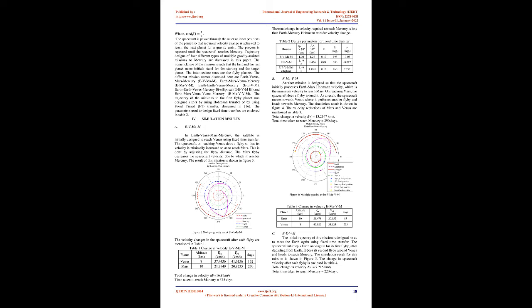3. Multiple gravity-assisted mission. A multiple gravity-assisted mission involves the use of more than one planet for gravity-assisted maneuver. Trajectories can be designed initially to reach either Mars or Venus since these planets lie next to Earth. The first gravity assist can take place as soon as the spacecraft reaches the first planet. If the spacecraft passes through the inner circular position, then the velocity of the spacecraft decreases. However, the velocity of the spacecraft increases if it passes through the outer circular position of the planet.